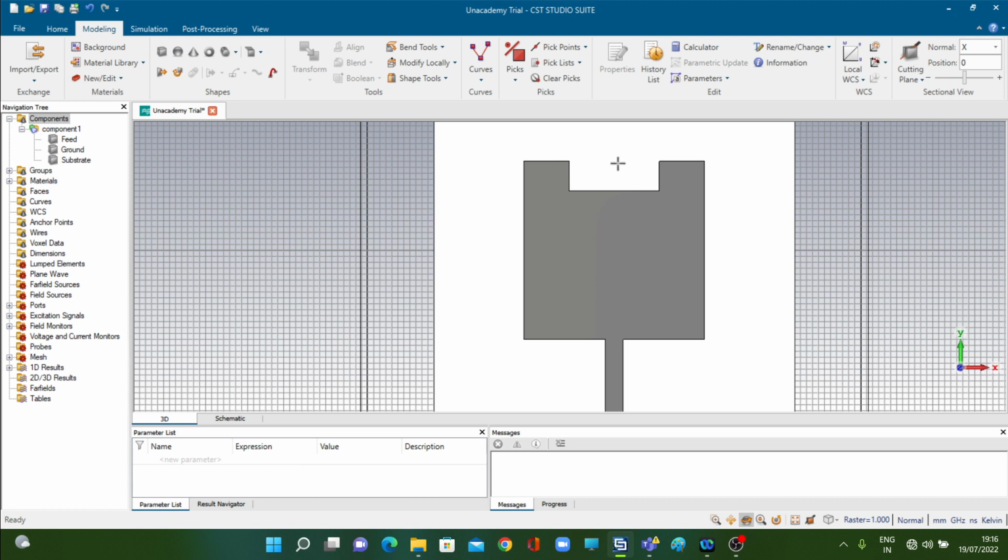Among them, why is this Hilbert fractal the most used one? Because the Hilbert fractal deals with rectangular edges, or vertical or horizontal edges. So it is easier to design. But it does not mean that rectangular slots, vertical and horizontal edges are the only option that we have. We can have triangular fractals also. We can cut out triangles also. That will give us Sierpinski carpet and Sierpinski gasket. You can Google and see the structures of them.